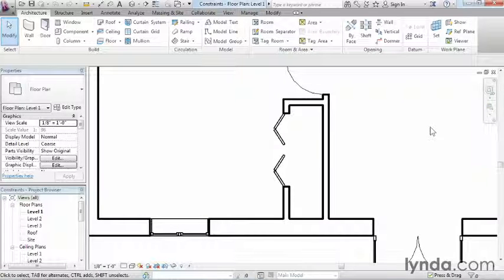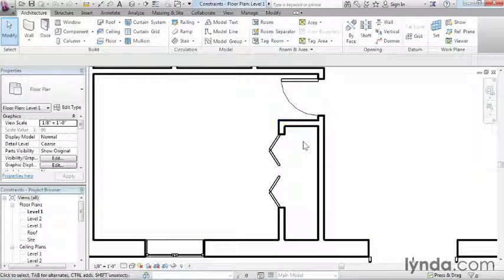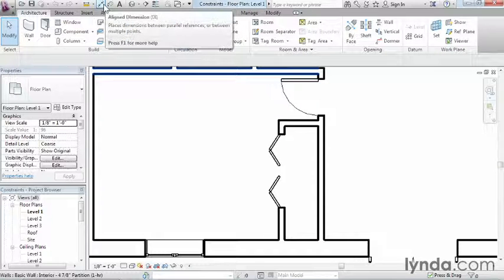And you can see two small problems. One is that I don't have a whole lot of room for the doorway right there, so I might want to reduce the size of this closet slightly. And two, this door in the closet's not centered. Now, perhaps I'm going to consider a few different positions for this door. So what I can do is build a relationship between the door and the closet. And it's going to start with a permanent dimension.